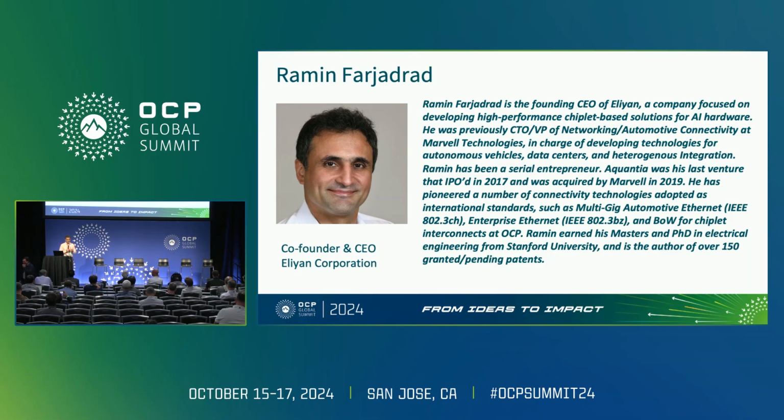So good afternoon, ladies and gentlemen. A little bit of background on me: I've been designing wireline transceivers for most of my life, almost 30 years. Back in the 90s, I started working on maybe some of the first CMOS multi-gig SerDes, as we call it today, a name that came up afterwards. The 5 gig SerDes, and also the first PAM4 SerDes, which I proposed in order to build a 10 gig link in almost half a micron technology. That enabled us to run at half speed and also helped with the interconnect.